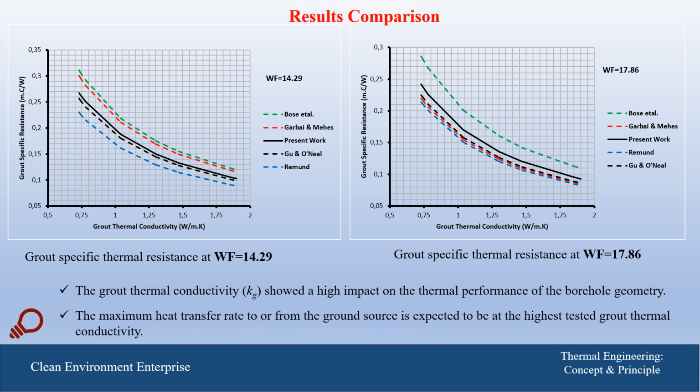At the same time, we may expect that the lower thermal resistance will accompany the higher thermal conductivity, which is reflected, of course, on the depth of the borehole and the cost for the final design of the borehole heat exchanger.